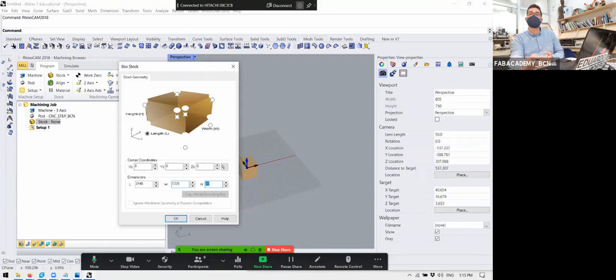Let's put the thickness of the material. Always the same as the laser cut, we measure with the caliper in the different corners. As we are using the full size, usually measure in 6 areas and take the highest value. In general, I know that 15 is not 15, it's 15.5 or 14.5.